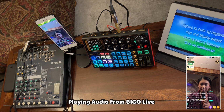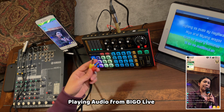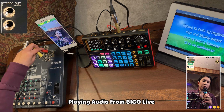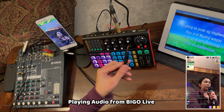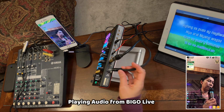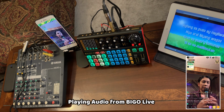And next, we will connect this mixer to the K300 live sound card. So I will connect this end over here, the TS dual mono, the one that looks like that, to this mixer, to the one that's for stereo out. Okay, there you go. And then the other end, the 3.5 millimeter TRS, I will connect this one to here, to the one for mic 1. Okay, just make sure it is plugged in properly, otherwise it will not work.